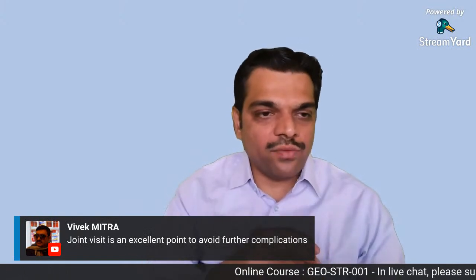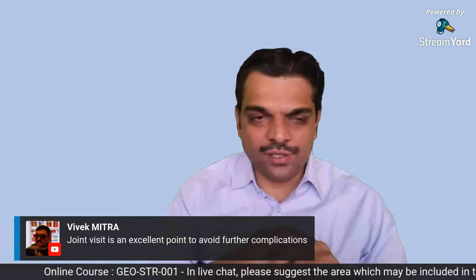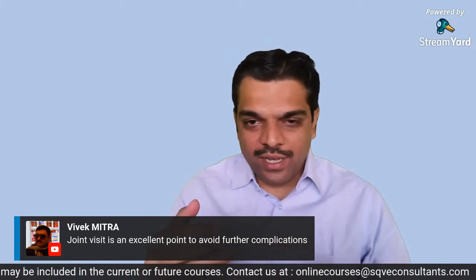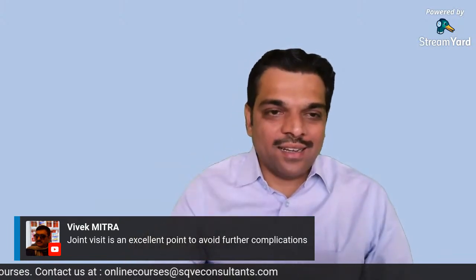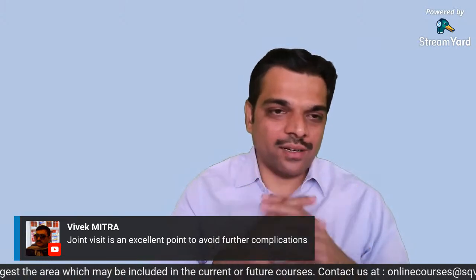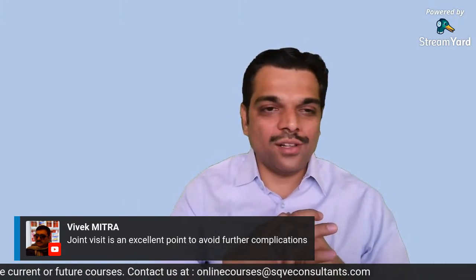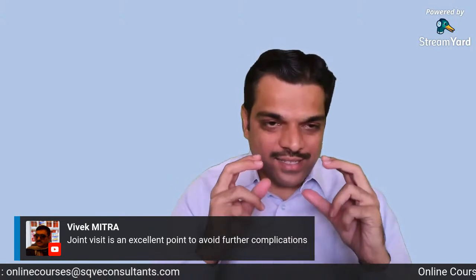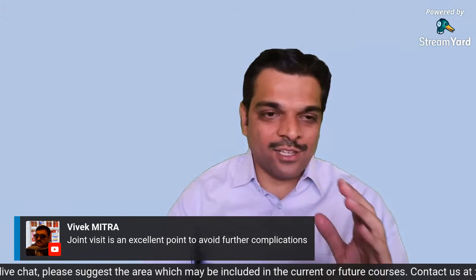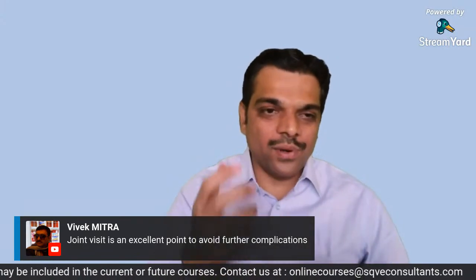Okay, Vivek Mitra is saying that the joint visit is an excellent point to avoid further complications. Yeah, I think this is an excellent point which someone has suggested, that the joint visit must be there so that on-site decisions can be taken. See, let's say if my structure is executed and then I come to know about the problems, it's very difficult to rectify. For example, let's say I have built the entire structure and then there are settlement issues. Now retrofitting the structure is extremely difficult and extremely time consuming, and it involves a very great amount of cost. But if we have a process wherein there is a joint visit, and let's say we have altered the type of foundation so that we could avoid that kind of settlement in the structure, then I think it's a great saving for the structure, right? And then as you rightly said, it can avoid all further big complications.